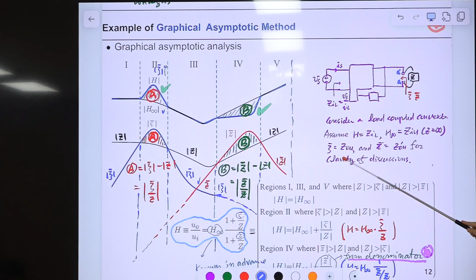So that is the regular output impedance, GOU. OU means output impedance, U means uncoupled converter. So we know this, right? Because we designed and analyzed this, we have complete knowledge about this converter. We designed the control loop, everything, so we know everything. Then we can evaluate the output impedance of this uncoupled converter. You can evaluate, simulate or measure with a current sink load.